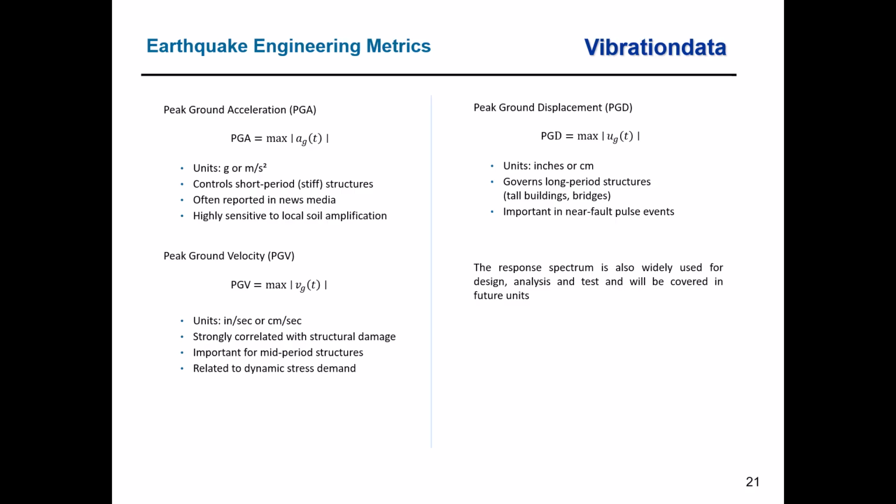There's another metric we're going to get into. In aerospace, where I kind of come from, it's called shock response spectrum. And in the world of earthquake engineering, it's called modal response spectrum analysis. It's another way of assessing damage potential, and it accounts for the natural frequency or family of natural frequencies that buildings might have at a fixed damping ratio. We'll talk quite a bit about those in future classes. So more fun to look forward to.